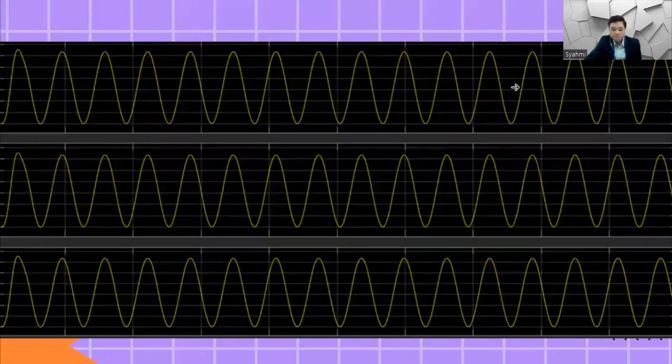So the demodulation of the DSB signal is to retrieve the original message signal, and coherent demodulation is typically employed because it requires the carrier signal in the demodulator to be synchronized in frequency and phase with the carrier used in the modulator. Then the DSB-SC signal is multiplied again by the synchronized carrier signal, effectively shifting the spectrum back to the baseband.